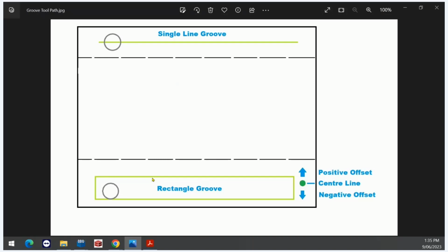So if you want a profile door through Doormaster LT, obviously your shark nose is on the back of the door, you're machining the front of the door. Unless you have 6-face machining set up, it won't machine both. It will still display both, but it won't be able to machine both.